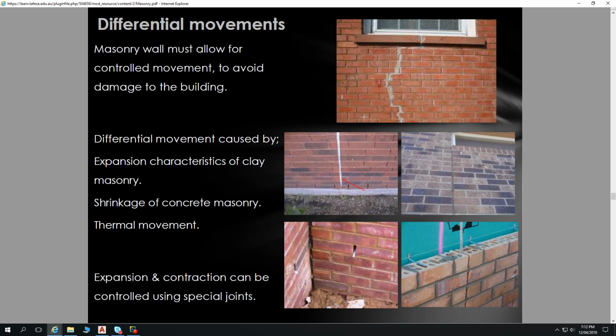If we get a crack which is doing that, then we can be sure that either we've got very strong heave happening right at a point next to something that's dead stable, or possibly heave happening next to subsidence shearing that.